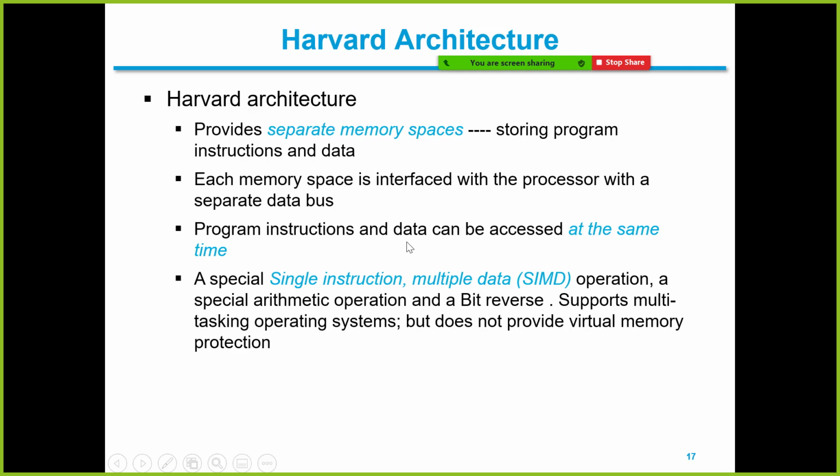Harvard architecture. This architecture is a little bit more complicated. It provides a separate memory space to store program instructions and data, and each memory space is interfaced with the processor with a separate data bus, so the program instructions and data can be accessed at the same time.